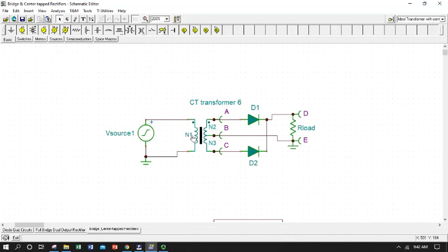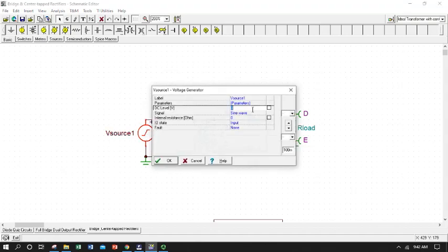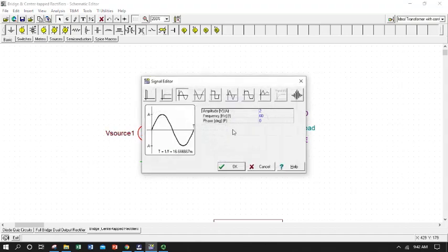and you can choose your number of input coils and your total output, and then it'll split that evenly between N2 and N3, because that's what center means. The tap is at the center there. So on this circuit, we've got a sinusoidal input into our primary of 2 volts at 60 hertz.